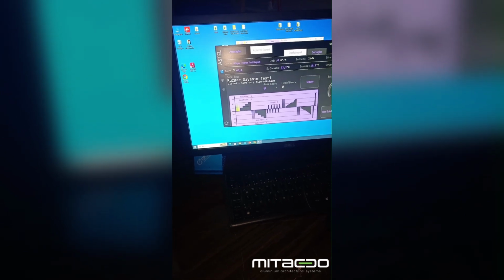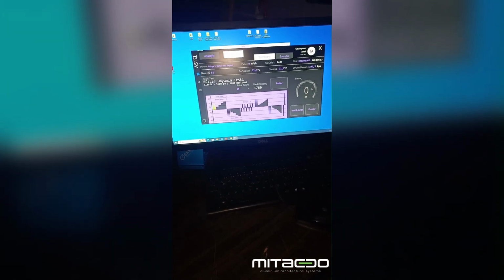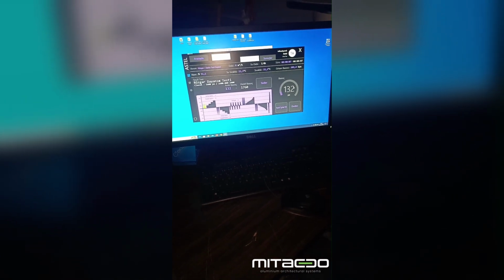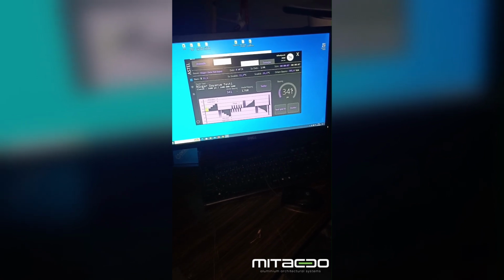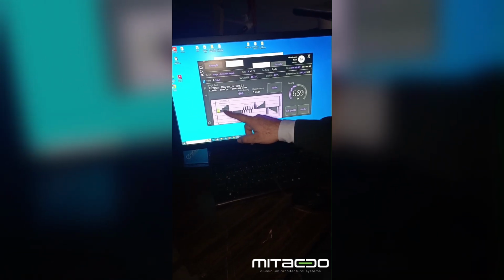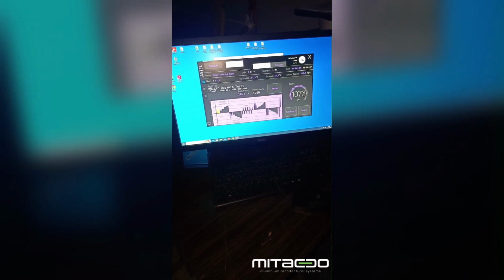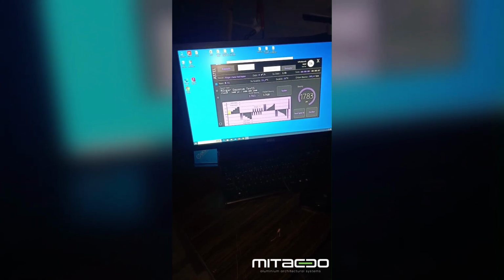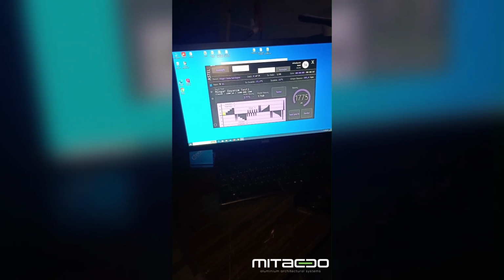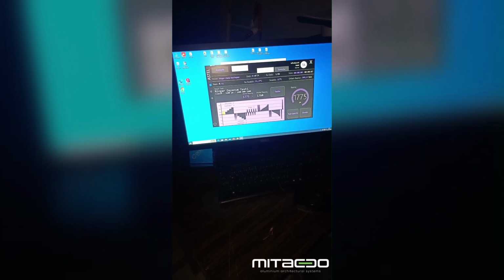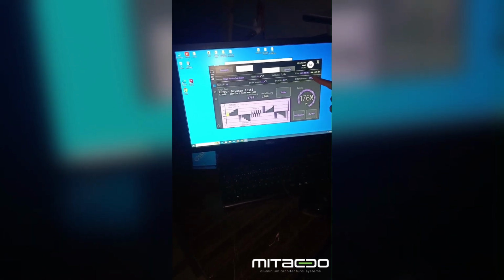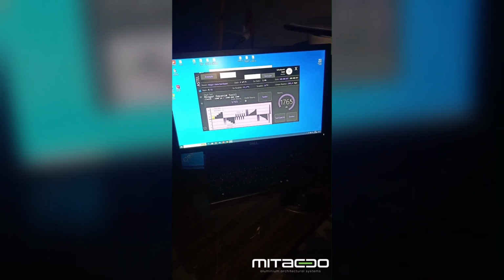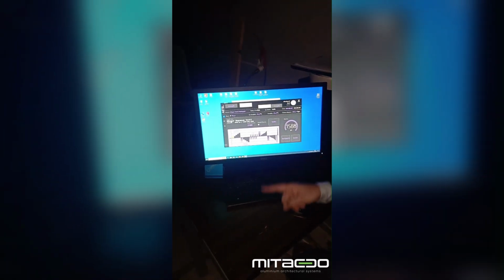It will rise up to 1,760 pascals. It will wait 7 seconds after exiting. After waiting 7 seconds, it will decrease to 0 pascals again and the pulses will end. From now on, the system will go up to a maximum of 1,600 pascals for deflection and wind resistance. It will do this in all 4 levels. It will wait 7 seconds at each level. It's currently on a 7-second cooldown. After 7 seconds it will go down to 0, wait there, finish the impact part and wait for our command.